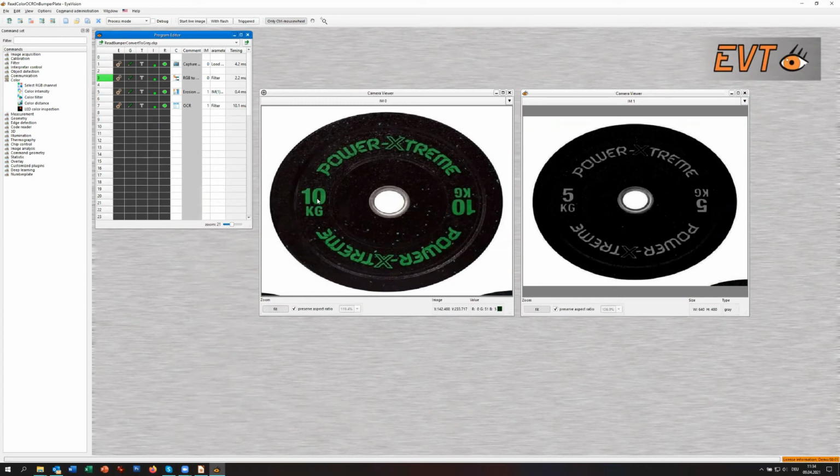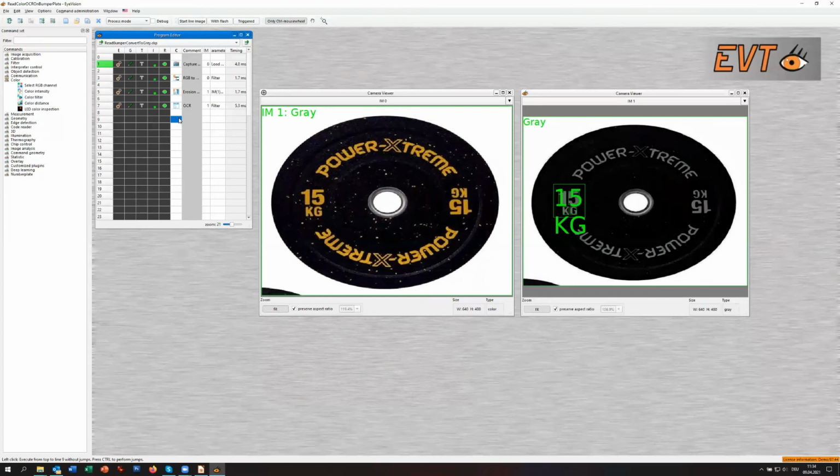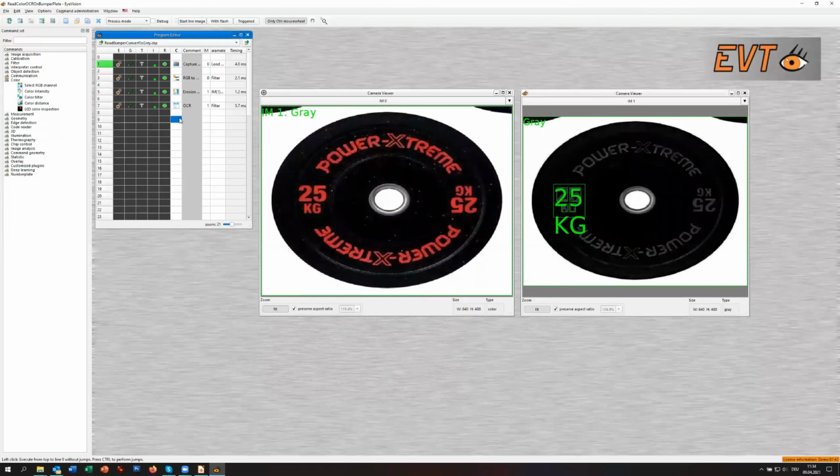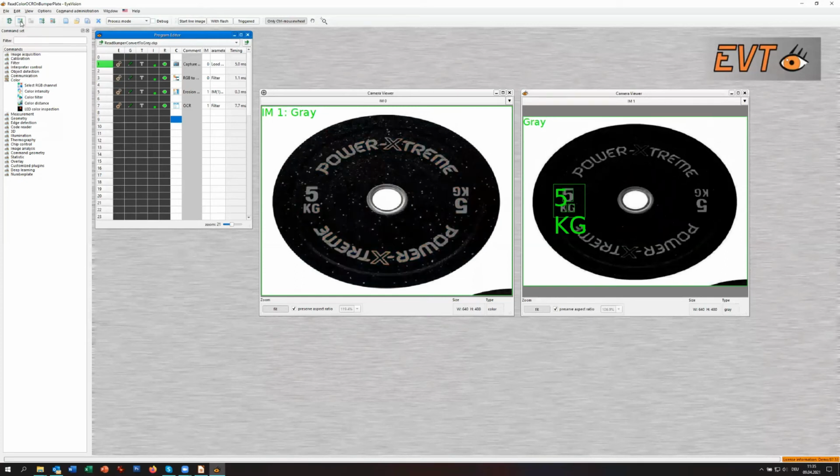So you can select, okay, I want to have green. If you know it's only green, you can optimize it for green and generate, based on this filter, the optimal gray contrast on which the OCR is working. In this case, because these colors are really disjunct, it's very easy to do it simply with an RGB to gray conversion. You don't have to do more.